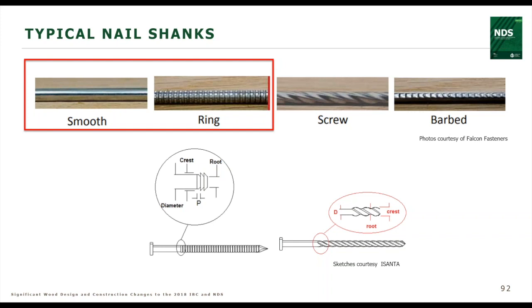But an important thing that you may want to note is when you're looking at a ring shank nail, ring shank nails are created by machinery and tooling. They deform a smooth shank nail that is made from pulling a round wire. So you'd start with a smooth shank nail, you deform that shank by compressing part of the nail and rolling it. And this forms this root diameter, which you can see expressed. So that's kind of the narrowest part of the nail.